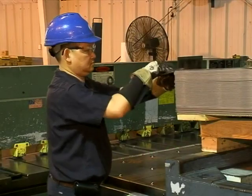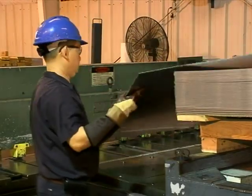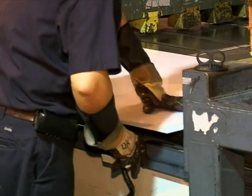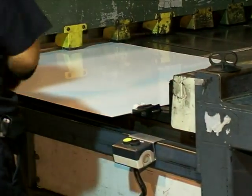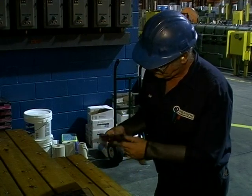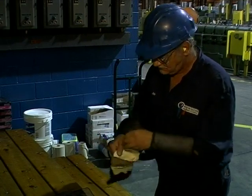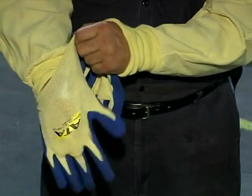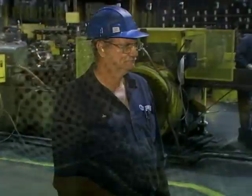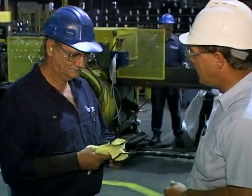Synthetic fiber gloves offer a measure of protection, but they do not make you invincible. Caution is still required even when using the best PPE. Before using gloves, inspect them thoroughly for cracks, punctures, or tears in the material. Make sure they are the proper size and allow enough strength and dexterity to safely perform the task at hand. If the gloves are in any way defective, dispose of them immediately and obtain a new pair.